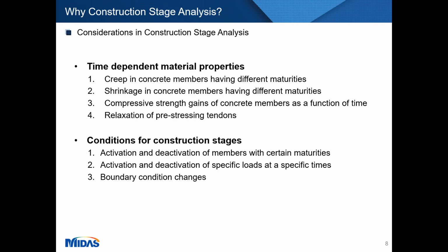Then compressive strength: as you know, the strength increases with time, and the concrete achieves fck in 28 days. So that's why we need to take that effect into account as well. Then conditions for construction stages. Now, the activation or deactivation of members with certain maturities needs to be taken into account, as well as when the loads are activated.